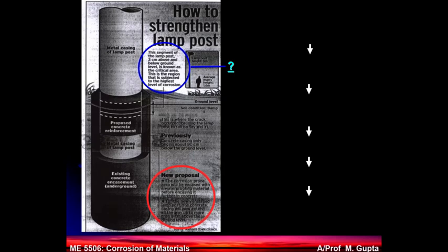If no one can protect iron now, then waterline corrosion sets in, where the difference in the oxygen amount at the surface level and below the surface level makes an oxygen concentration cell. Less oxygen becomes anodic, more oxygen becomes cathodic. So the damage starts happening below the ground.